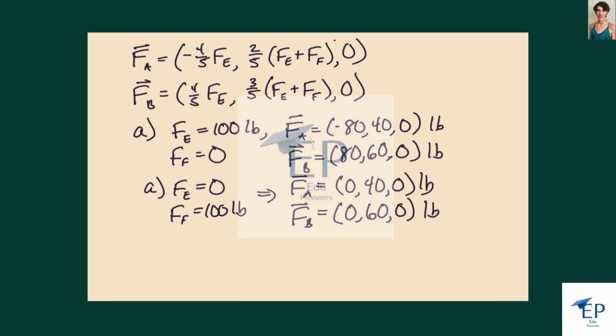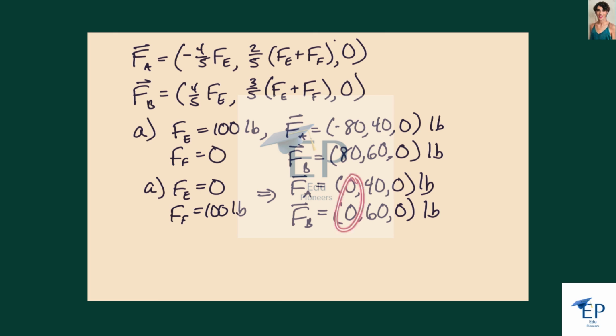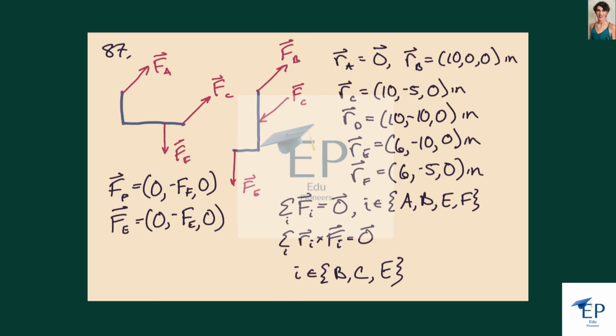And if we apply the load at point F, which is up here on this upper bar, we see that the horizontal component of our reaction forces is 0, because we're not creating a moment that needs to be offset. Here we're creating a moment that is causing the horizontal components in these reaction forces. But when we apply it up here, then we aren't, and then this being in equilibrium, FC, I believe in this case, is also just purely vertical.